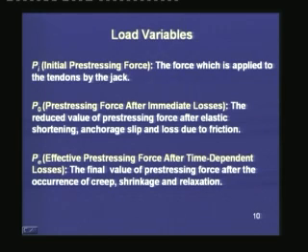The third one is PE, which is the effective prestressing force after the time dependent losses. As we learned earlier, the prestressing force drops with time, and after several years it gets stabilized to a final value, and that value will be referred to as the effective prestressing force, and it will be denoted as PE.